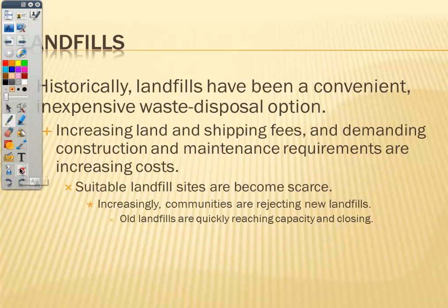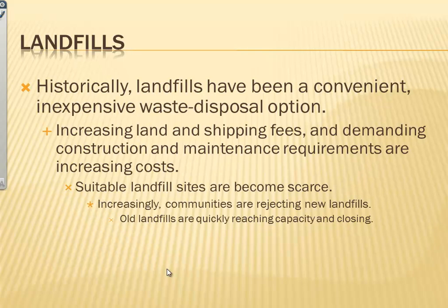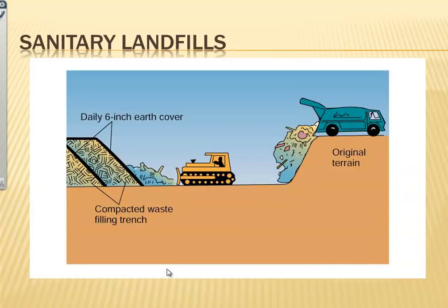So we created these sanitary landfills, and still there's a problem today, but not as bad as there was in the past. And we'll take a look at how we should make a modern landfill, one that's suitable. It's very simple. They come, they dump, they create a depression in the ground, keeping it away from places where groundwater gets very close to the surface. They bring the trash in, they compact the trash, put a layer of soil, and then continue to do that until the entire hole is filled in.